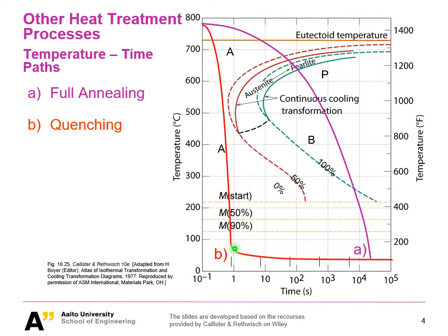That's why when you have oversaturated carbon in your iron matrix, you will not be able to have BCC. It has to be BCT, because the carbon wants to go away and couldn't. That creates stresses, and that's why it creates this BCT. So it is basically a consequence of the oversaturation of carbon, which cannot go away from the iron and has to be dissolved in the iron matrix.